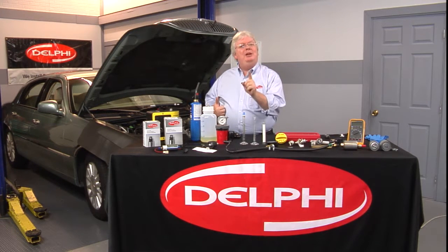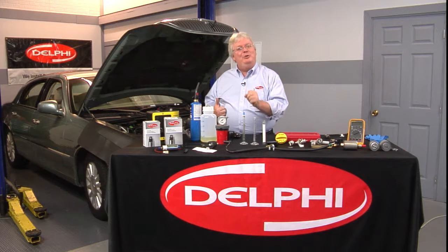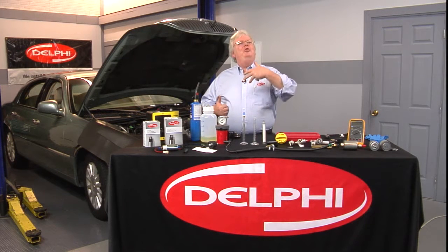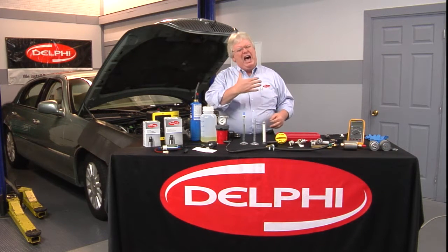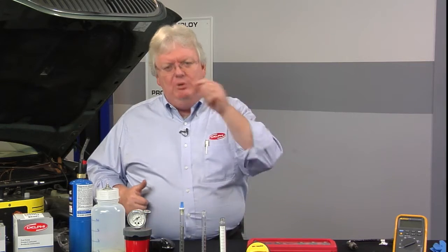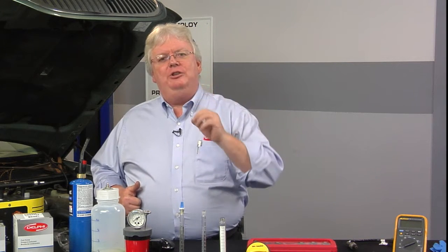If you remember, sometimes you saw a little bit of a negative fuel trim because it really didn't have an air-fuel management issue. It had an idle speed issue at speed density. On a mass airflow vehicle, a different story entirely. D would be the correct answer on a mass airflow equipped vehicle. If we had a big air leak, you'd see the fuel trim go up and you'd see the vacuum voltage on the MAP sensor also go up as well. So the correct answer can go either way depending on the vehicle, slightly higher, slightly lower, if you have an air leak on speed density vehicles.